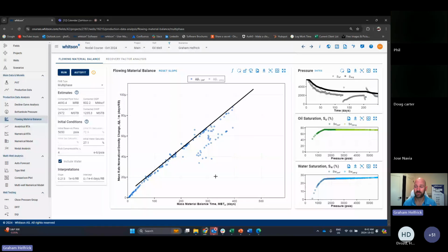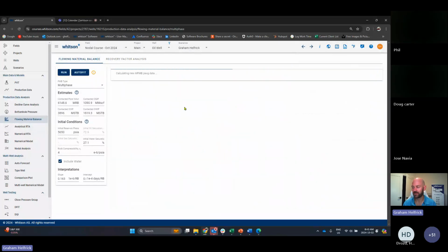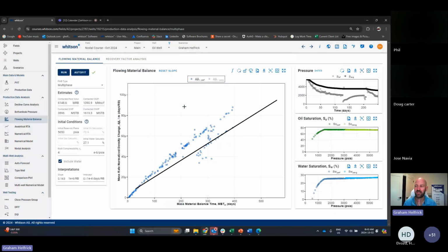and potentially low. There's a couple ideas we have to make that fact a little more obvious and even bracket the range of reservoir pressures when you're not seeing the entire drainage area. So what you said is totally valid. Yeah. I guess on the other side of things, I see production engineers using the original reservoir pressure for IPR curves sometimes, which is often an overestimate of the remaining pressure. So you kind of have to pick your poison, right? Which way do you want to go? Let's see here. As long as our current reservoir pressure is around the 3,100 pound mark on the black line.